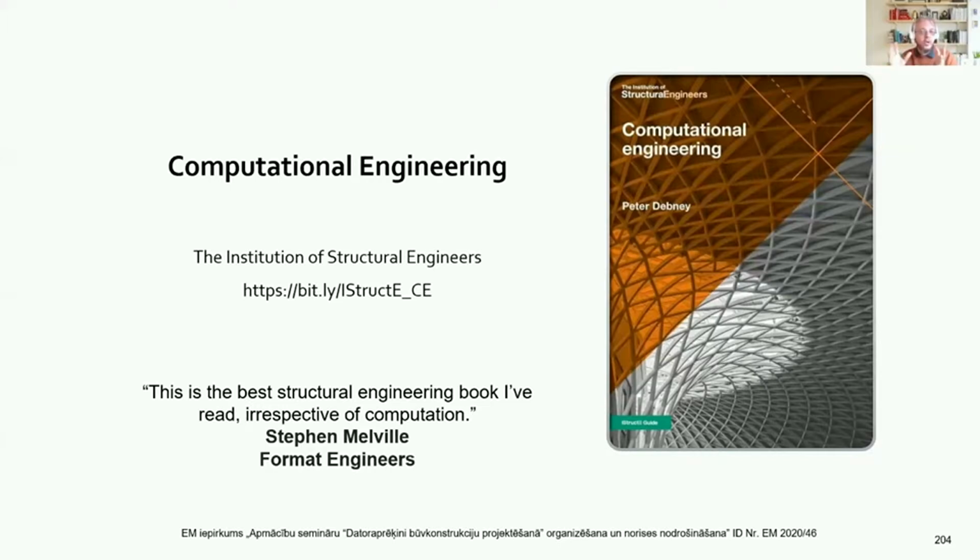Also, of course, Euler buckling. If you take the conservative approach, take the narrow section, a quick Euler buckling calculation gives you an approximate answer. You can do the large section and the small section, and the answer will be somewhere in between the two.